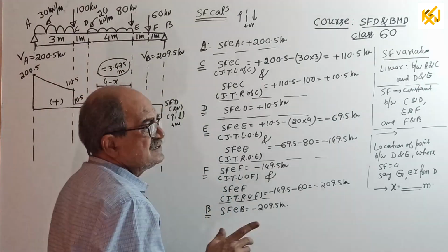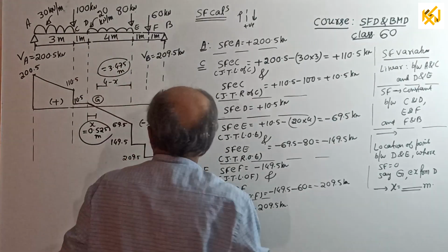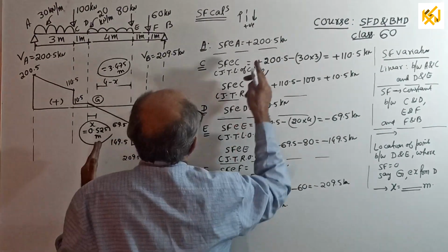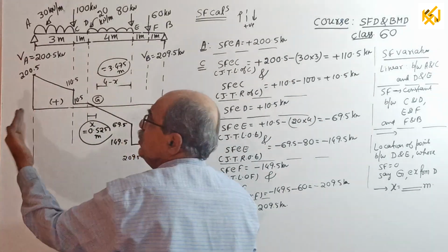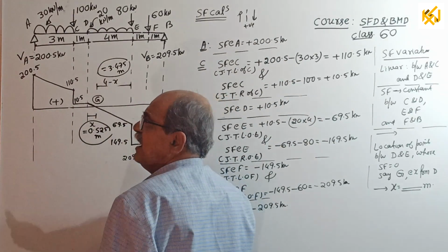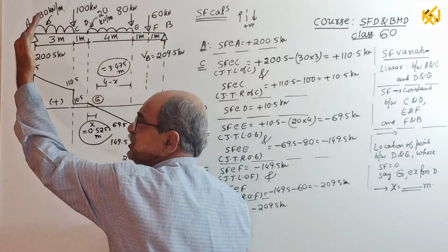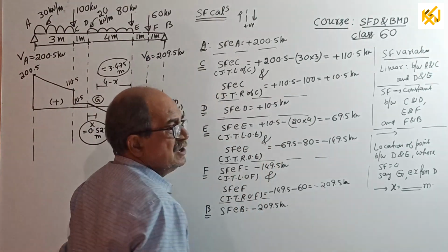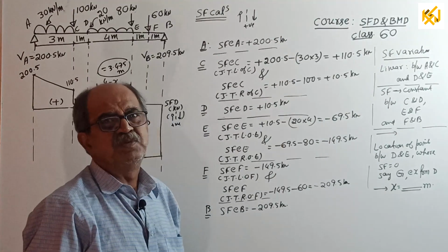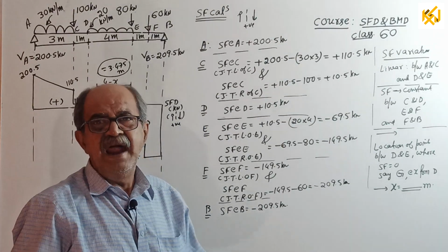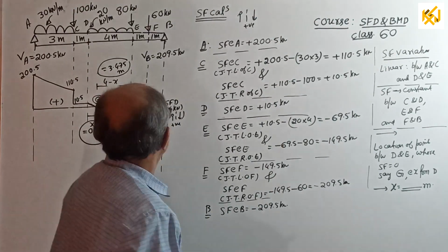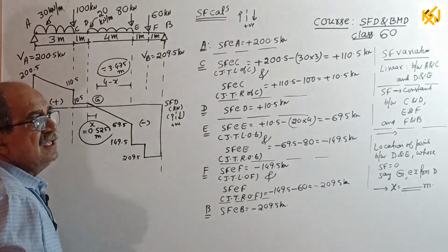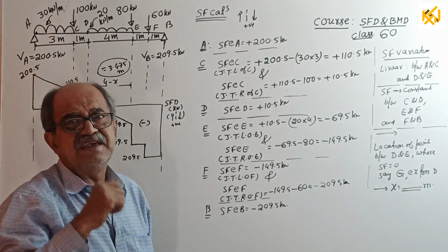Okay, today I will tell last time. You start from there. Since you start the calculation from left side, our convention is what? Left up positive. So when you come from that side, any upward force will be positive shear, any downward force will be negative shear. That's all. So I don't have to keep on telling this one every class. I will tell later once in a while. Okay, start. At A, come slightly right side or technically slightly inside.